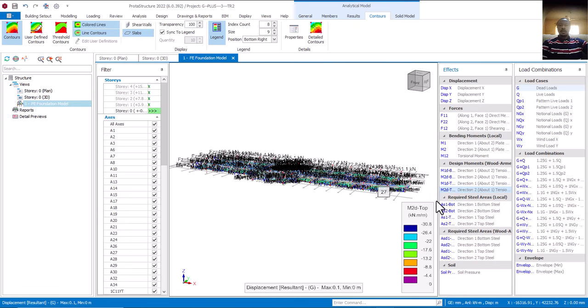So that is that. And if you have increased from 200 to 250 and you follow the same process up to this stage, and you now click on any of this one here or here, and it's still giving you that error, you can go back and increase up to what? 300. That's the maximum, I think so. Yes, maximum. In fact, if you have increased to 250 and it's still giving you that, you can ignore it, because if you look at the way we model it, our slab is not the one carrying the load. What is carrying the load is what? It's our beams. So that's why our construction should now be on the beam, not on the slab. Is that okay? Because a slab thickness of 200 is very, very okay. So if you have done that and it's still giving you any warning, then you can ignore it and move on. Is that okay?